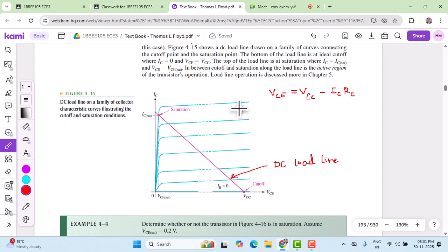And next is going to be the derating, the power derating. The maximum power dissipation depends on the temperature, which is generally specified at 25 degrees Celsius. For higher temperatures, we should look at the data sheets. So let us see how the derating factor is determined. Generally, the derating factor is given in terms of positive or negative. Here it is going to be 2 milliwatt per degree Celsius. That is going to be the derating factor. Based on this, we can estimate the power dissipation at other temperatures also. That's where the derating factor helps us.